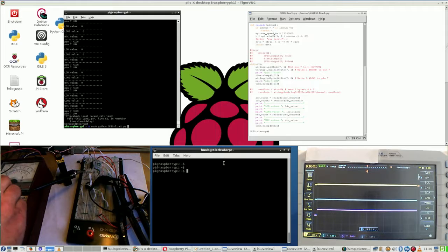So the voltage is absolutely 0. Am I measuring correctly? Well, I can go here on the multimeter to 3 volts measuring. So instead of 30 it will be 3. And then it says nothing either. And here no surprise.